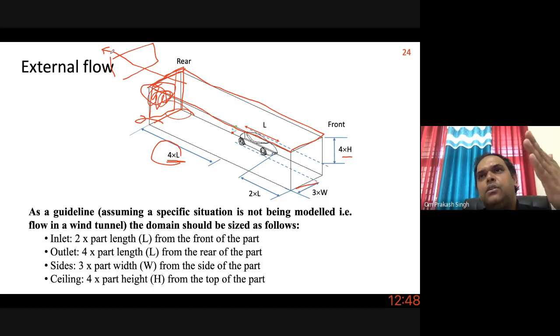And there you can fix whatever boundary condition you want to apply, not only fluid boundary conditions, there can also be other boundary conditions, like atmospheric boundary conditions. Only then is it possible to have a converged solution, when your outlet is free of any disturbance and recirculation zones.